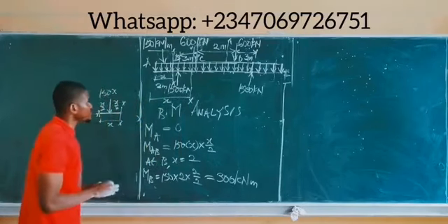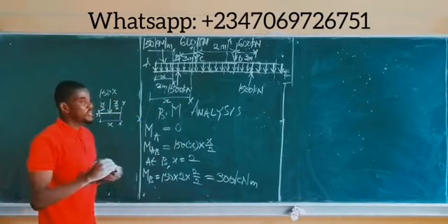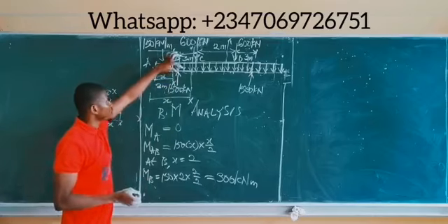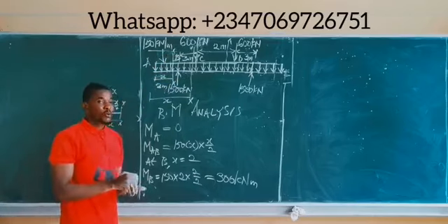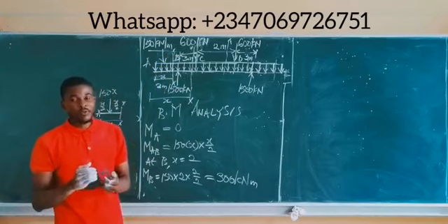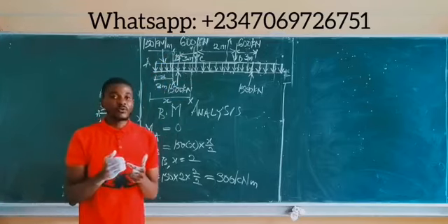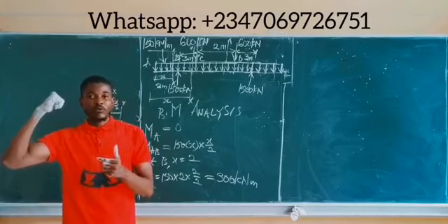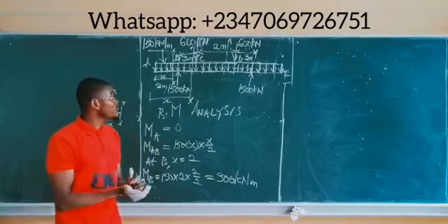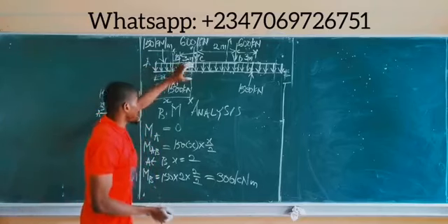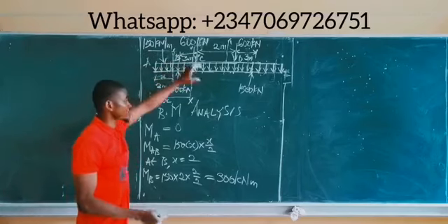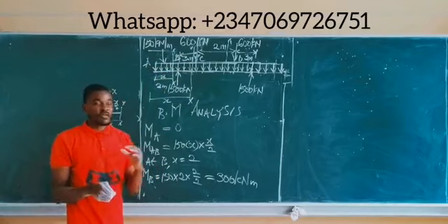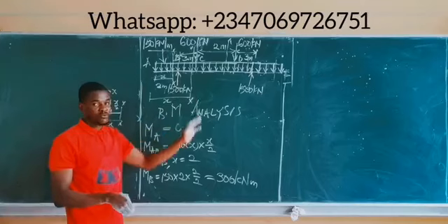Now, in shear force analysis, we found the length of the UDL between point B and the point of section, but it doesn't work so with bending moment, simply because when taking moment, after you move past the point, you consider all the forces behind and take moment of those forces about the new point. So since from point A to the point of section I still have the UDL running, I have to consider the moment of that UDL force from point A about the point of section.